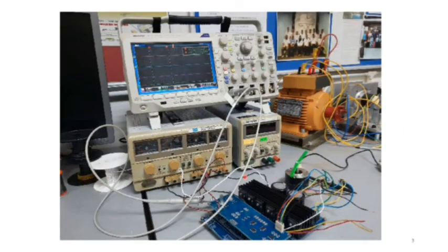Then we assemble all of the prototypes. We have a 3-phase inverter prototype. Then at the bottom one we have a gate driver circuit, and the upper one is the controller. Then we connect it to the BLDC motor. There is the positive and the ground. The positive one is the red one, and the ground is the black. Then we have phase A, phase B, and also phase C. Then we connect it to the oscilloscope and also the power supply.